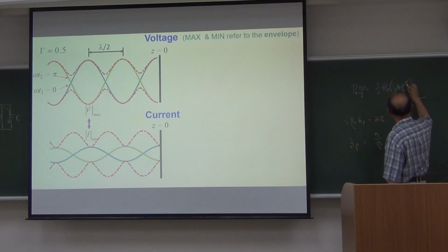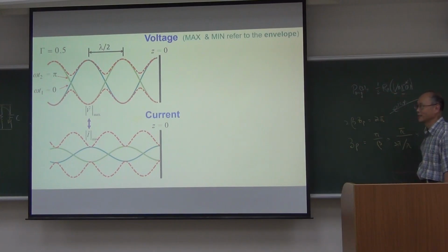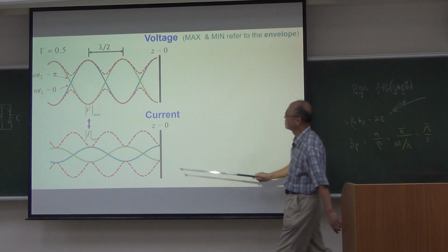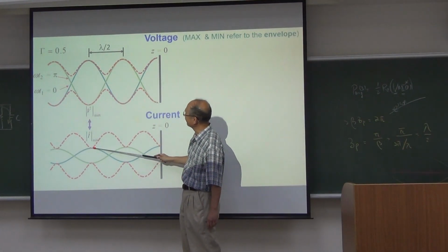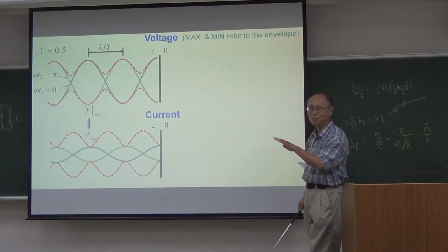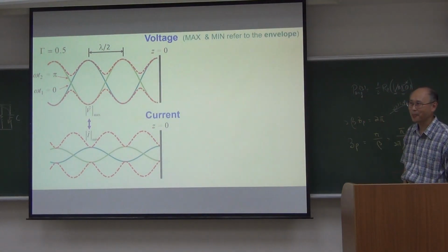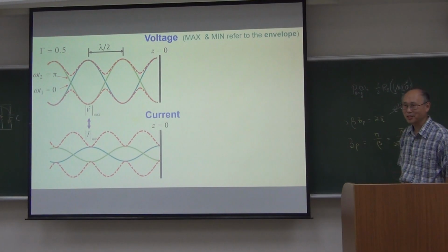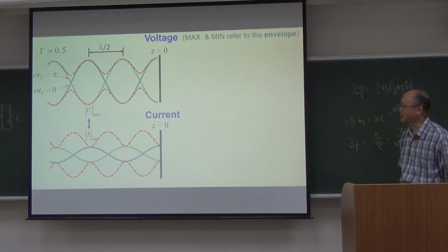This is a function of t. So when one gets larger the other gets smaller, to keep constant power on the transmission line. Does it make sense to you? It should. Right? Because it's a lossless transmission line, so you have this kind of complementary pattern.